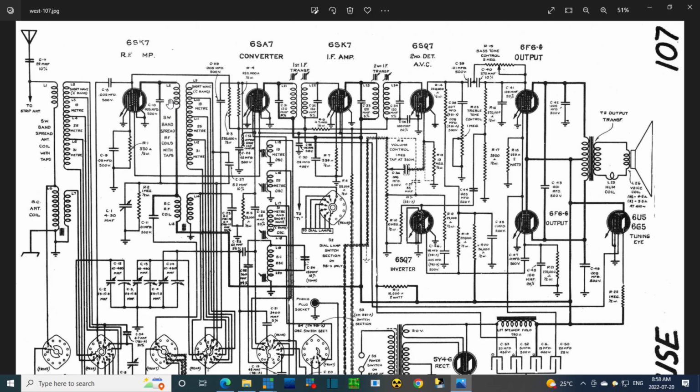And could this quiet the radio? Now this is an interesting question. Oh yes, absolutely. If this were to short right out, there's bad things that could happen. It could burn out this coil. This is a bad guy to have a full short. But you saw when I tried to measure the resistance, it wasn't a full short. It continually, I guess, burned the short clear, probably repeatedly.